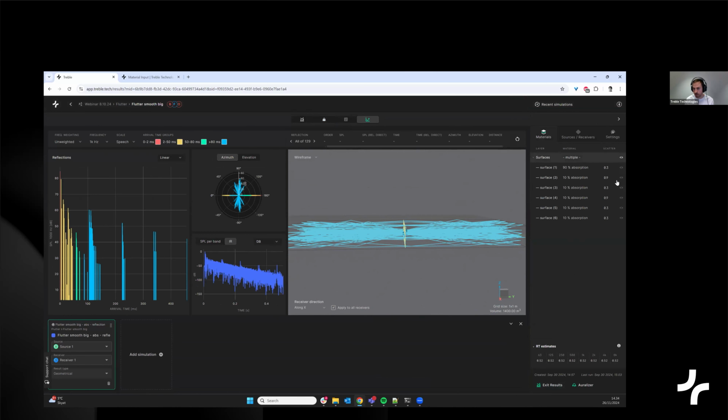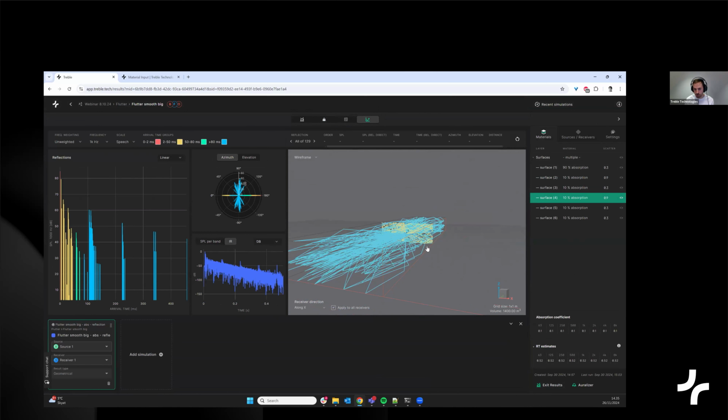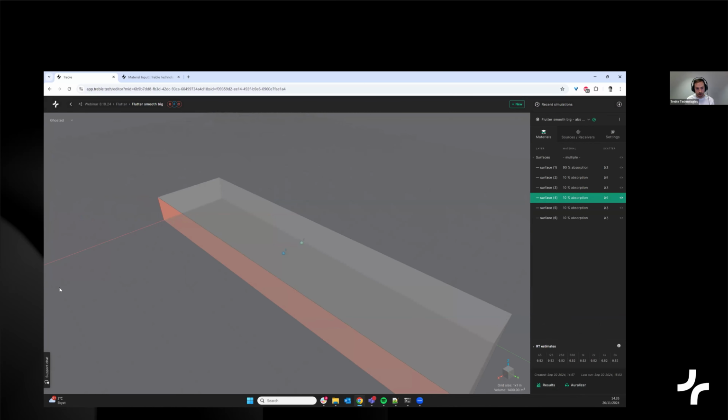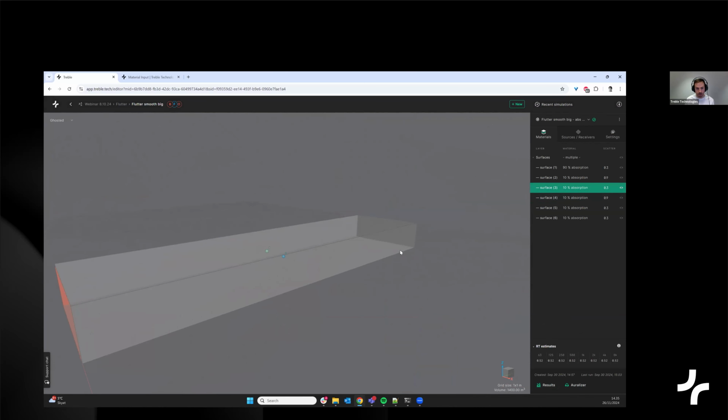So he added more scattering on the long edges from 0.3 to 0.9, meaning if you have some diffusive thing, like diffusers or more rough materials. Well, actually, we see it still in the reflectogram. So you can hear these strong reflections. And that means this comes from these here. And then, well, that means for this design, I would recommend adding some absorption.